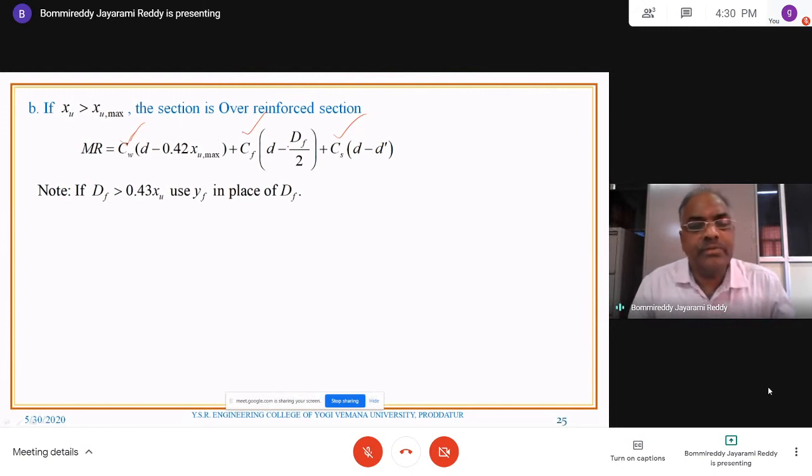Accordingly, you can find out the various terminology without any difficulty, because everywhere you see compressive resistance of web, compressive resistance of flange, compressive resistance of steel. Whatever compressive resistance of steel is used in doubly reinforced, same. And CW is the same as that of singly reinforced. And flange means it is the resistance due to flange. That is the additional part in case of flanged beams.